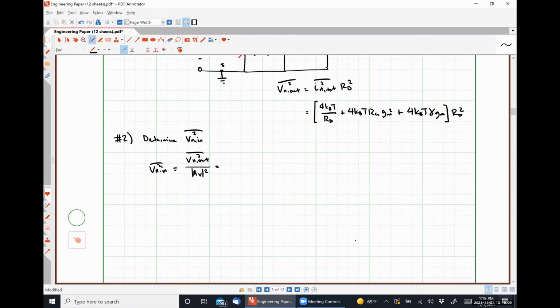So draw our small signal model. We're going to come back around to this guy here. We know that our gate has that resistor RG applied there. Here's our gate terminal. Here's where VGS occurs. Here is our source terminal. Here is our dependent current source, GM VGS. And since we're trying to find our gain, we no longer consider the source terminal to be grounded, right?